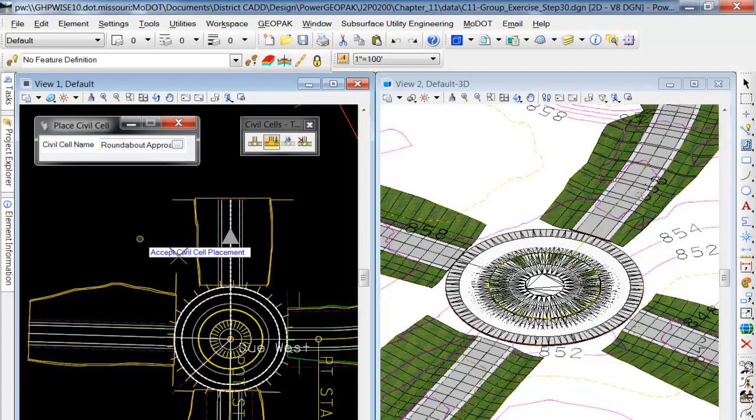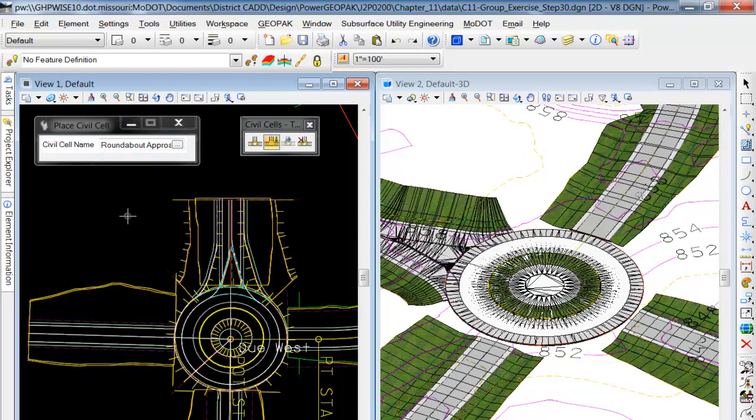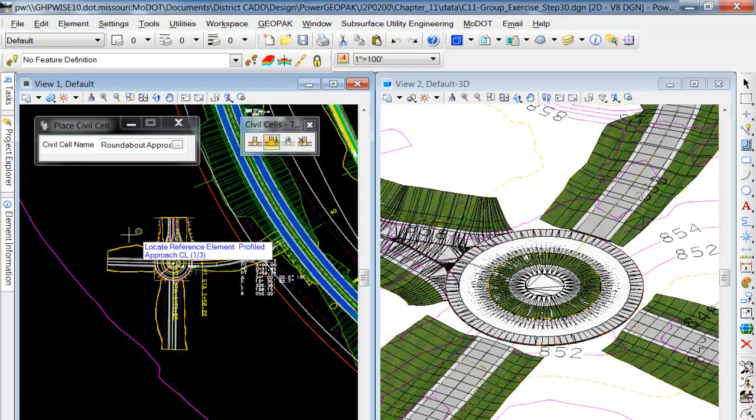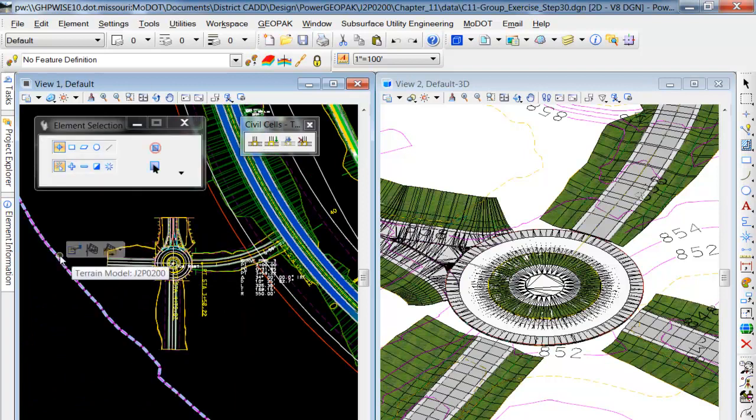The reason why I didn't worry about making my active ground, or my existing ground, active is you can see in that right window, we actually have end conditions out there. If nothing was active out there, you wouldn't see those green end conditions. All you would see would be our pavement. So I know I've got it active, but if you had to make it active, you just rest on that line out here, like we've done all throughout class, and then just set it active. But I can tell just by looking at that view that it is active. Okay.